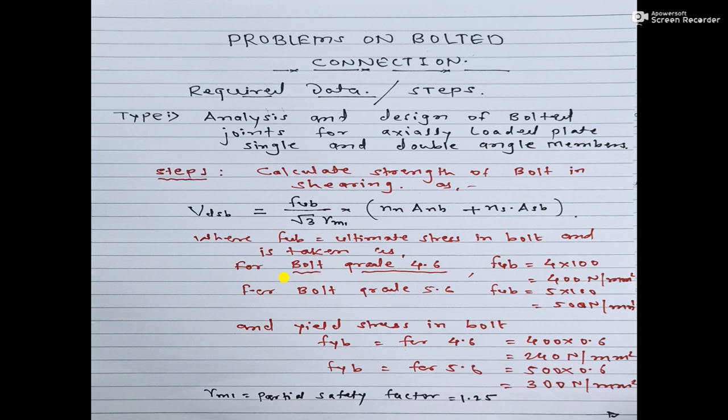When we apply the load, two forces act on the plates, also known as strengths, and these strengths may be in shearing or in bearing. So we have to calculate the strength of bolt in shearing and the strength of bolt in bearing. In the first step we are going to calculate the strength of bolt in shearing as